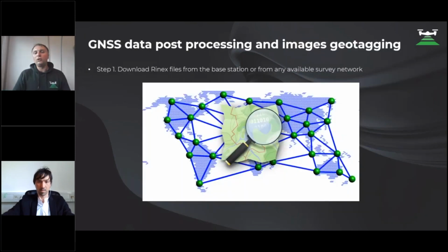And right now we will talk about the data processing workflow. First of all, I would like to show how to make photogrammetric data processing in 3Dsurvey using the TOPODRONE PPK system, with our software, to achieve accurate results and to minimize your field work, to exclude ground control points from processing and just use one ground control point to calibrate focal lengths to achieve very good accuracy in altitude. So I will show you.